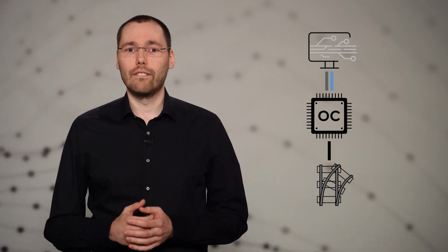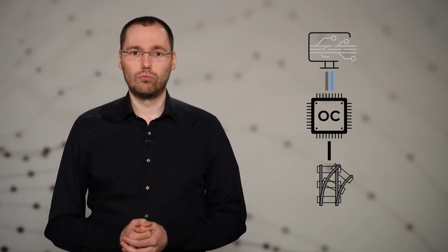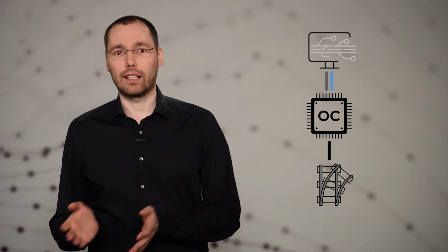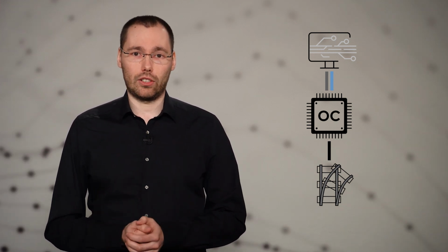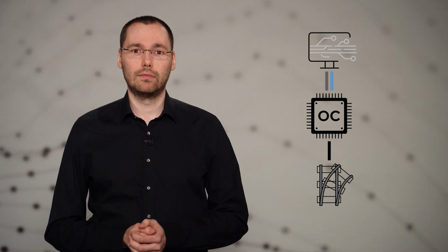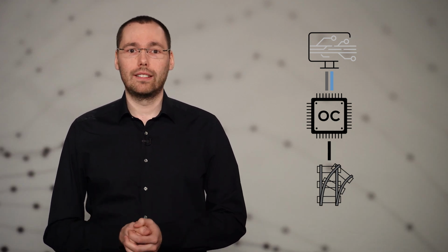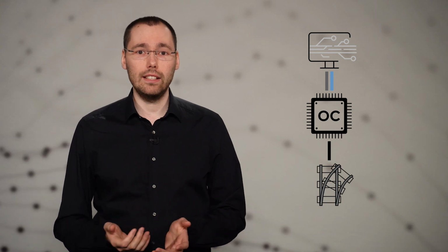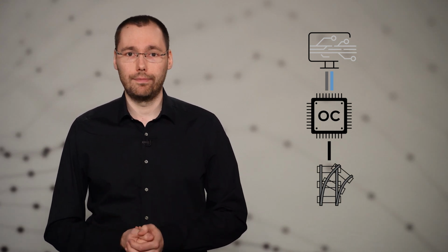We can imagine various test scenarios. Normal operation: switch from left to right and back again. Fault injection: simulate a stuck motor or delayed feedback. Communication loss: test the controller's behavior when interlocking messages are delayed, dropped or corrupted.